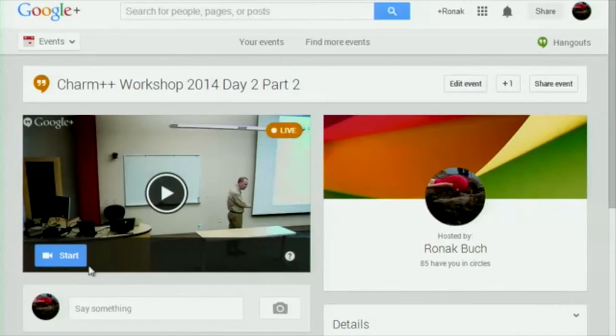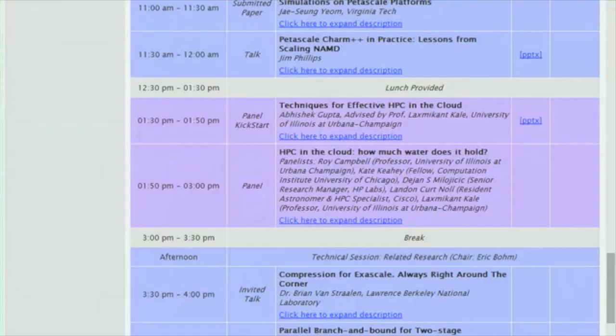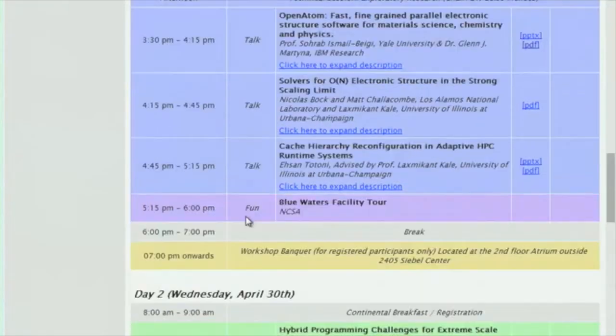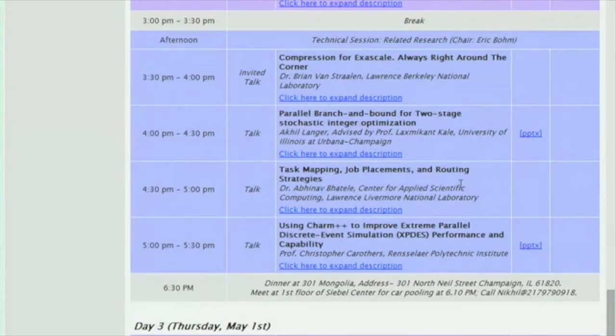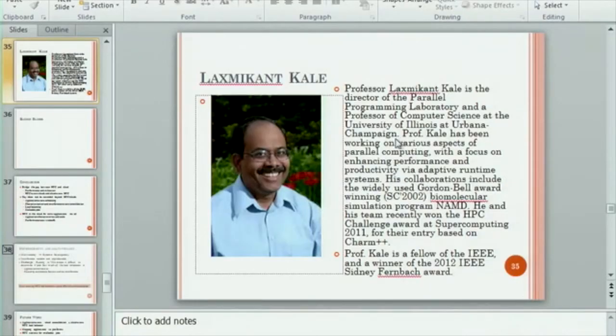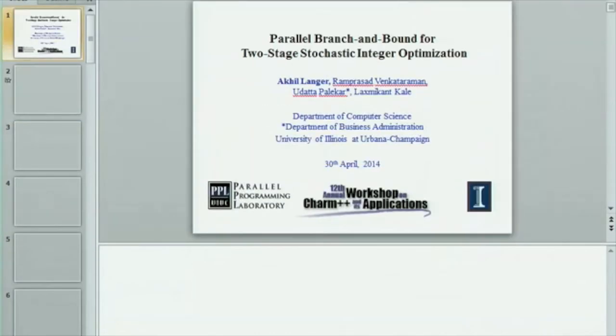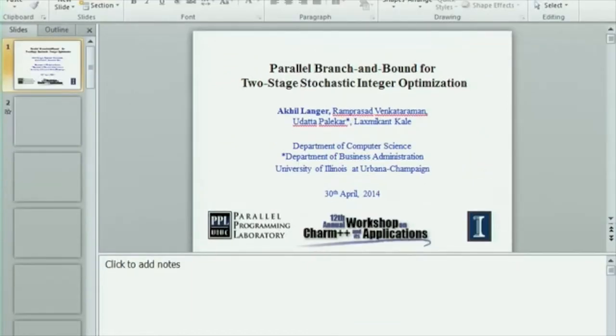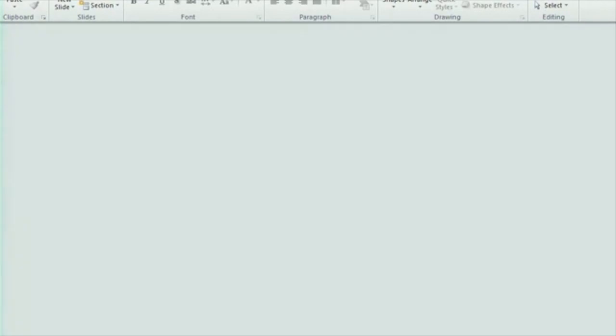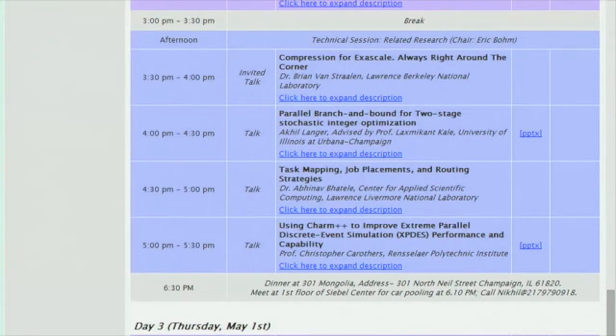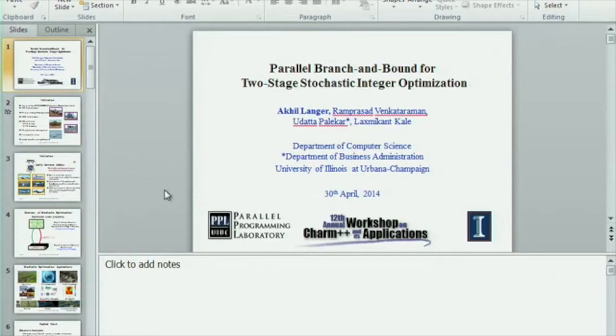I'm not sure I understood your numbers. I think you're telling me that the fastest I can get data is about 16 instruction cycles. So suppose I'm pretty numerical heavy and I need 5 cycles to process a word. That means I have 10 cycles to spare. So if your compression is more than 10 cycles per word, then I've lost, right? Because you now have delayed my access to the data by the excess. And so you were suggesting 35 cycles in a particular example.